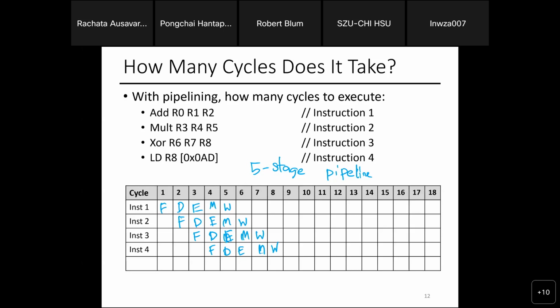So imagine your computer has, let's say, a 30-stage pipeline, compared to the 5-stage pipeline, which I can clock at maybe 1 gigahertz max if I want to design a 5-stage pipeline processor. Probably something like 1.5 gigahertz. Compared to the 30-stage pipeline on your computer, what's your clock these days? 3.5 gigahertz, maybe.